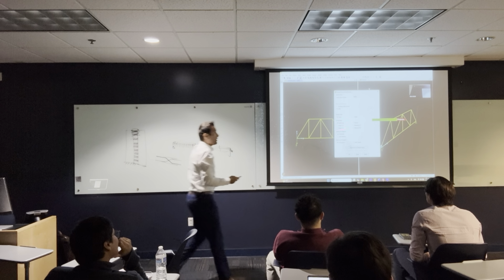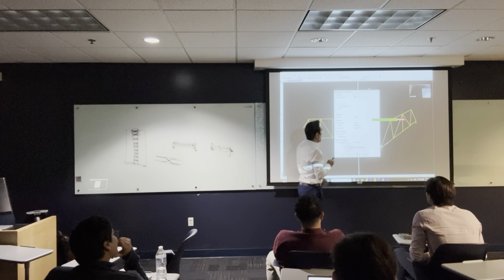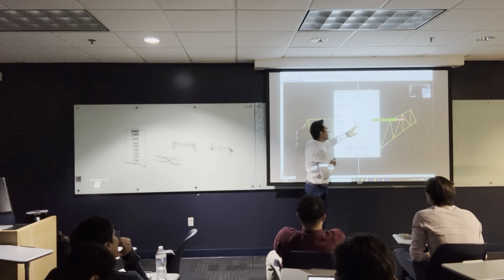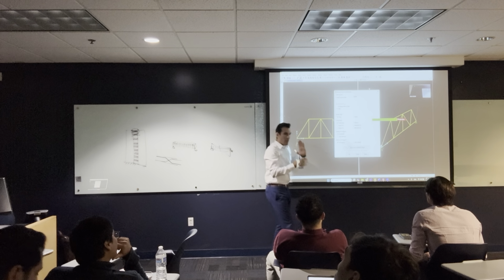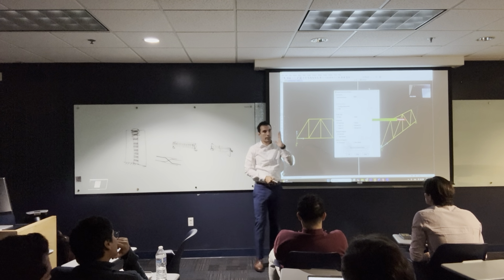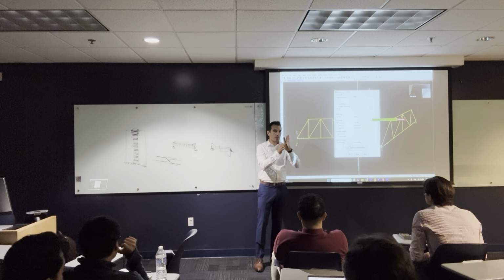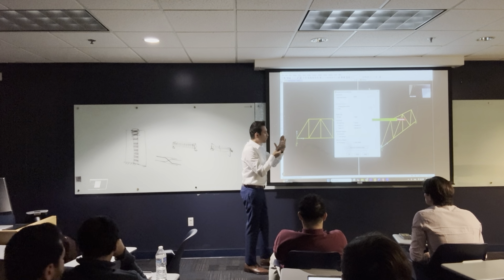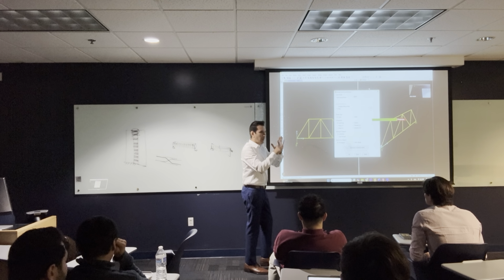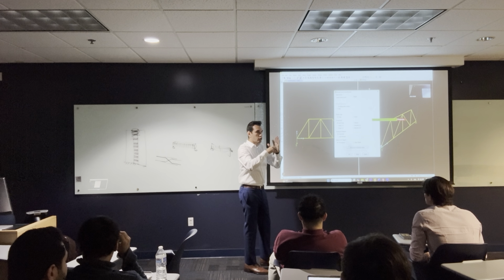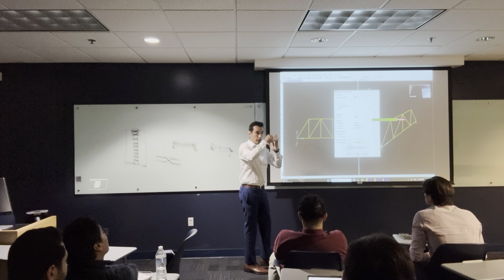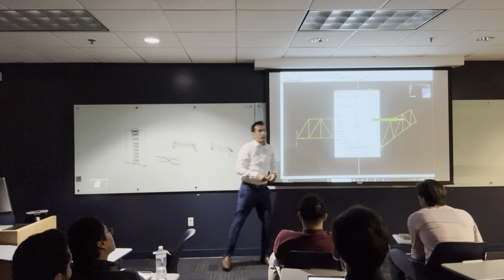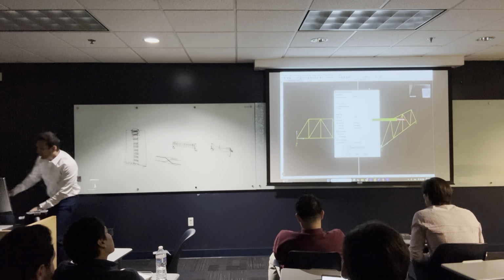Here it asks you, what internal forces do you want to see? Do you want to see axial force, like normal force? Or do you want to see shear 2-2 and shear 3-3 and moment 2-2 and moment 3-3? Do you guys remember? I told you our cross section is like this, and these are the directions. I believe it was 1, 2, and 3. So we're only interested in the shear in the 3 direction and the moment around 2, right? Okay. So let's see what we have here.